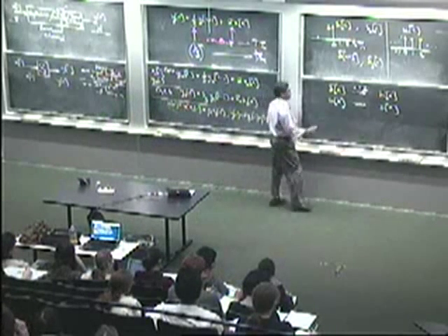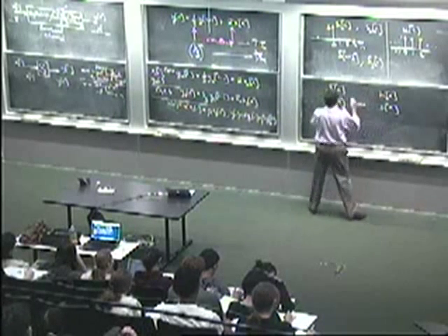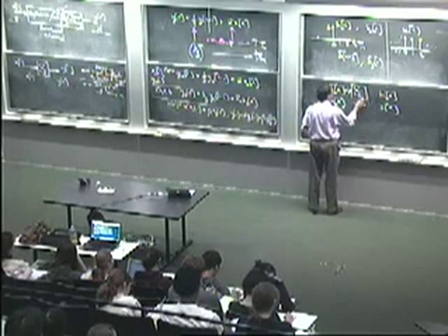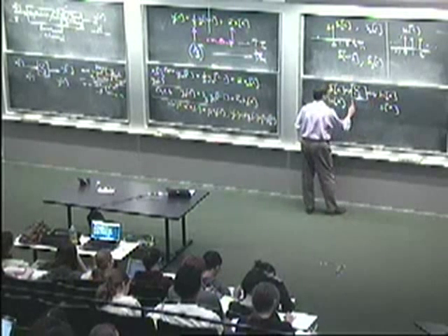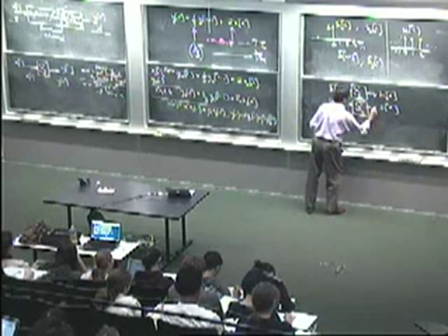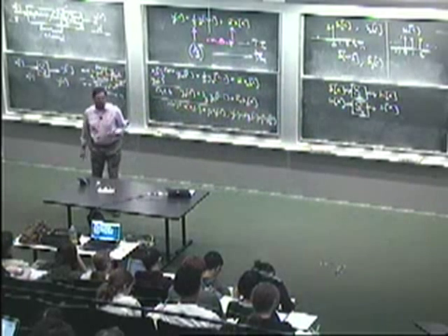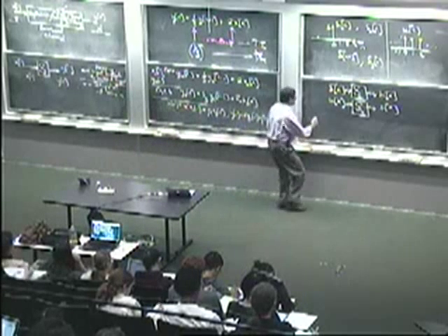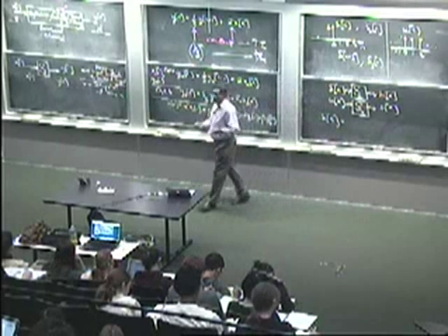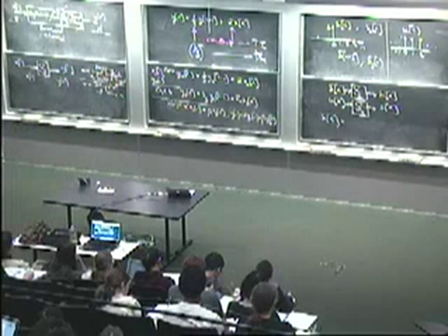So here's one way to think of that. This, by the way, is the same LTI system. Maybe I should indicate that more explicitly by saying it's a specific system, system 0. And with the same system, I'm trying to deduce the results of another experiment. So if we're thinking superposition, can you tell me how to write the unit sample function as a linear combination of unit step functions, maybe delayed unit step functions, scaled unit step functions?